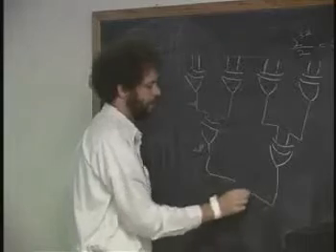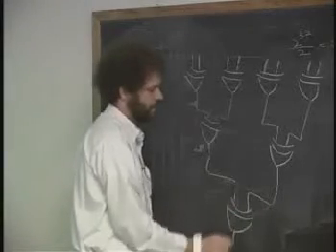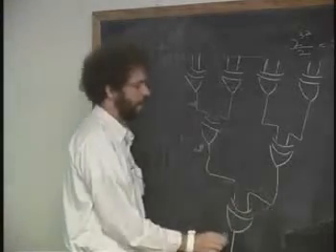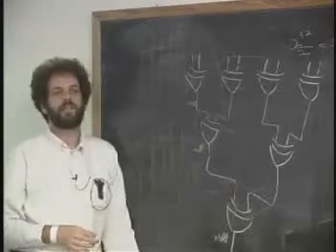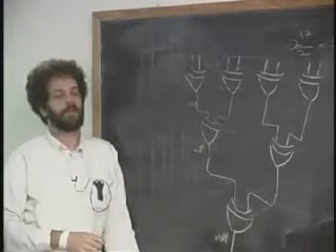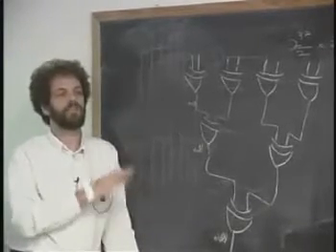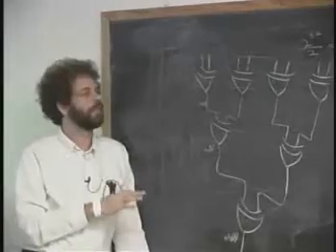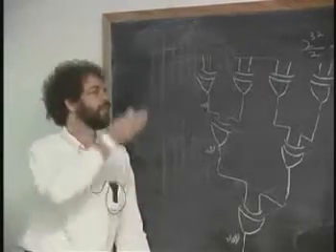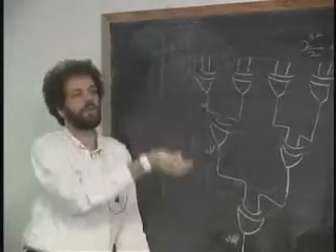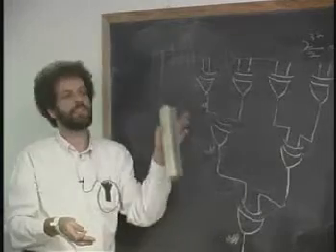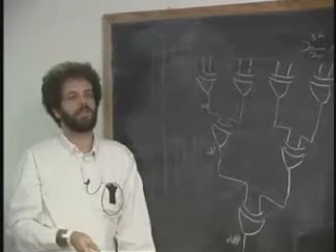And then I can take these two things, of course, and this tells me whether or not I have odd parity of 8 inputs. And so this is a tree. And it's a tree that is not, by any stretch of the imagination, sum of products form. It's not that I do an inversion and then an AND and then an OR. And yet it's only 3 levels deep. And it can handle 8 inputs.